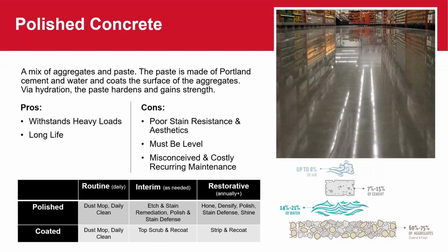So the pro of concrete is obviously it's everywhere, right? It's the base of everything we've got out there. It withstands heavy loads and has a very, very long life. The cons are stain and etching. Anytime you get something with a little acidity in it, whether it be ketchup or, heaven forbid, pickle juice or vinegar in a grocery setting, it's going to eat right through all of that polish and right into the floor.